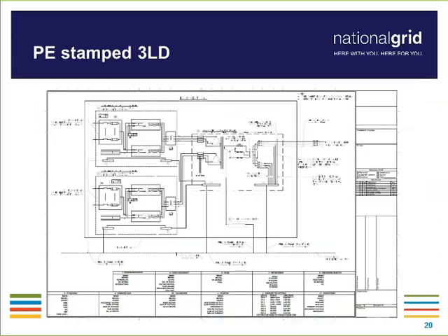Yes, thank you. So now the single line is very important. And somebody may ask the question, well, why would I need a single line and a three-line diagram? And that would be a fair question. Three-line diagrams provide more detail than the single-line diagram can offer, especially when it comes to three-phase arrangements. Now, the three-phase arrangement would distinctly identify transformer configurations, even though it may be stated on a single line.